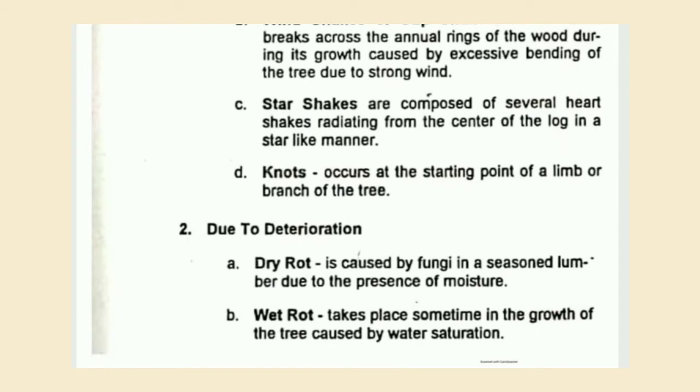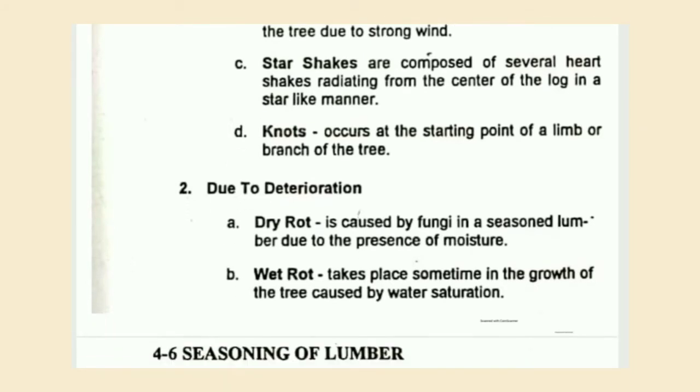Next are wind shakes or cup shakes, which are cracks or breaks across the annual rings of the wood during its growth, caused by excessive bending of the trees due to strong wind. Next are star shakes, which are composed of several heart shakes radiating from the center of the log in a star-like manner. Knots occur at the starting point of a limb or branch of the tree.